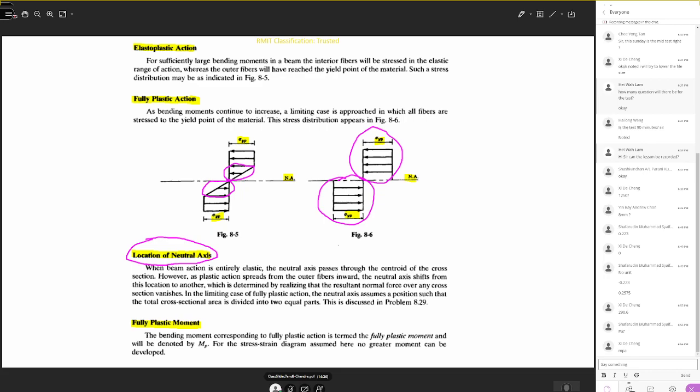Generally, we identify the neutral axis by applying the equation for the area. If you recall solid mechanics, we estimated the neutral axis y bar as sigma y bar dash a dash over sigma a, where sigma a is the total area. Here y bar dash is the centroid location of the individual rectangle, since the cross section may consist of a number of rectangles. So this is how we can locate the neutral axis under elastic conditions by applying the areas formula.